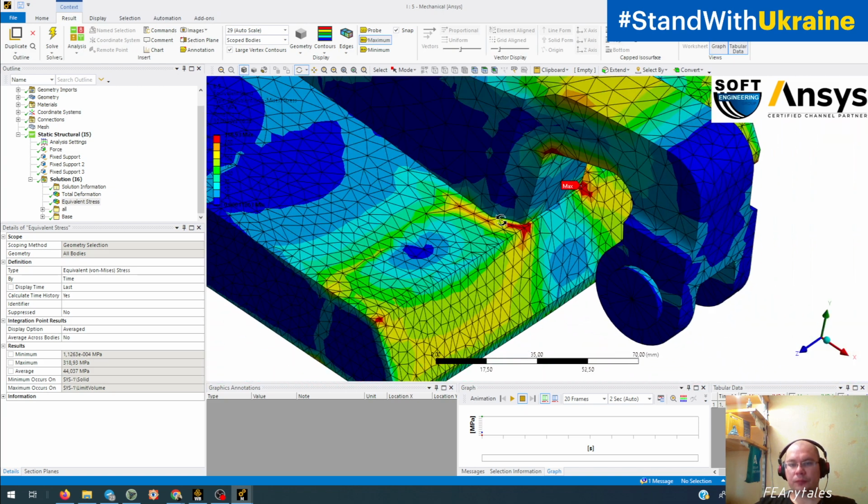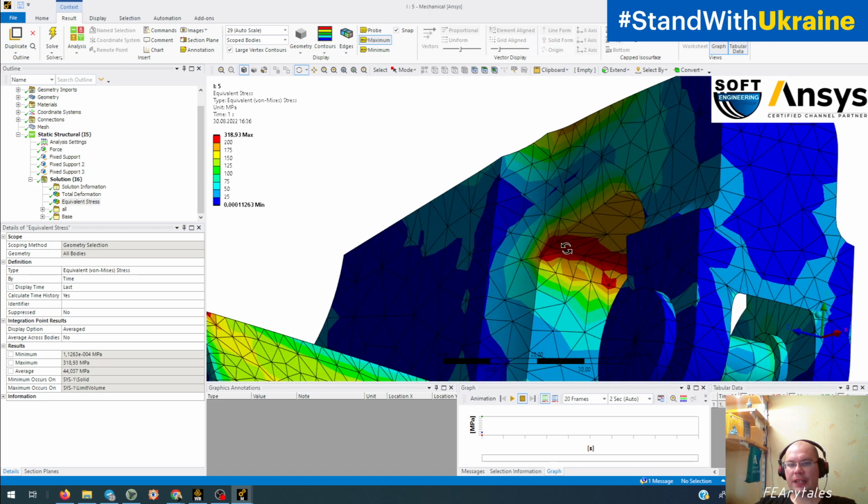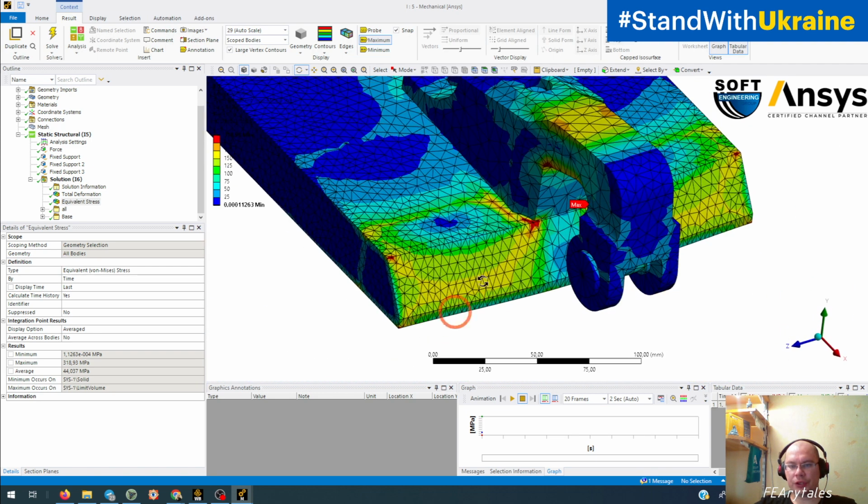So when you change size of your mesh, these stresses will go up sometimes, or will stay bigger, and they become adequate physical range and will stay on the same digit, on the same value. At this place, on the corner of fixation, you will have theoretically infinite stress.